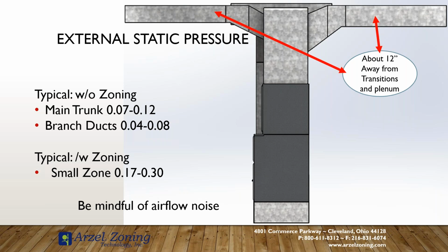And Manual D has a nice chart. Your return, according to the chart that I have in Manual D, and I don't think we discuss it in this PowerPoint. That's going to be in a different class where we go more in depth into duct design. But the chart has your supply duct designed a maximum of 900 feet per minute, I believe it was.